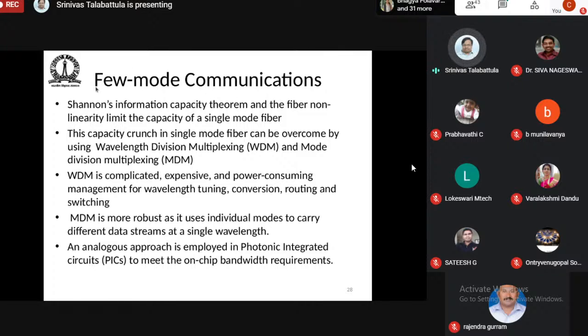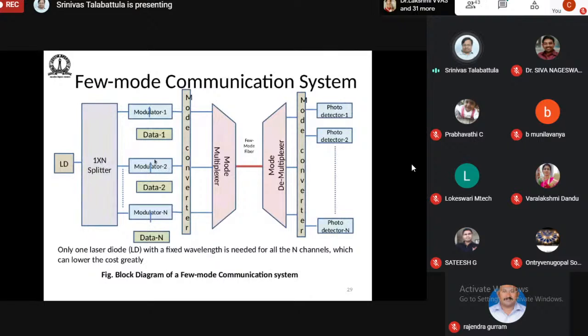And there's an advantage of using few mode. You can design an optical fiber with 2 or more modes, 4 modes, 8 modes, etc. Each mode can be manipulated or tackled separately, and then you can transmit a large amount of information. Many of you are aware of what is called WDM, wavelength division multiplexing. In contrast to TDM and FDM, WDM uses many wavelengths. Let me see whether there is a picture. Yes, let us use this picture to describe.